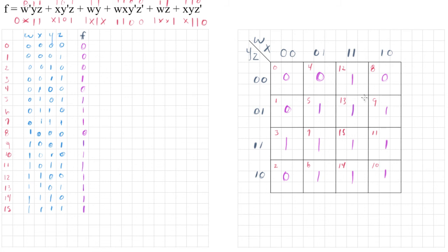Now that we've got our truth table transferred over to the K-map, we need to make sense of the data in the K-map. We need to group these ones together in the most efficient manner to get the best answer. Again, we can only take these certain ways. We can take them like this. Change color here. And just because I'm doing this doesn't mean that I'm actually going to do it that way, because you want to take the groups, you want to take as many ones as possible at the same time. For example, this.